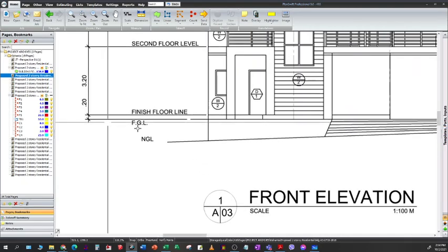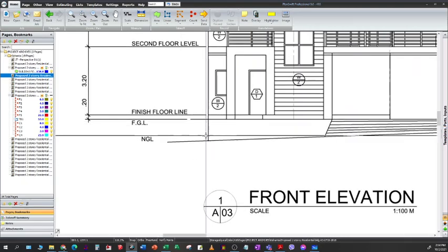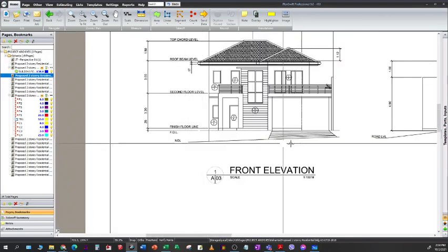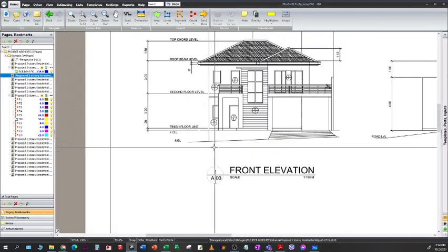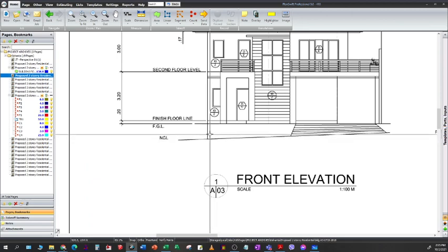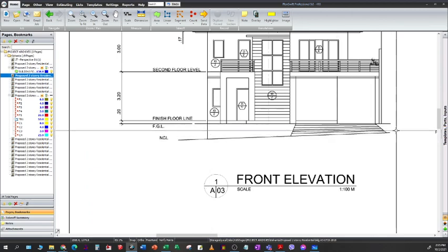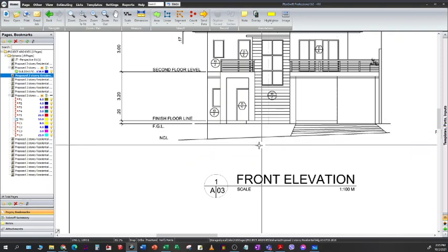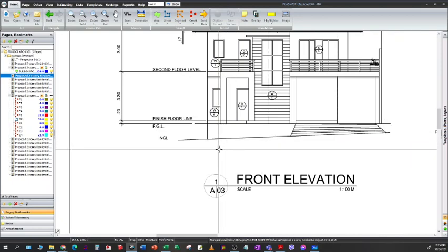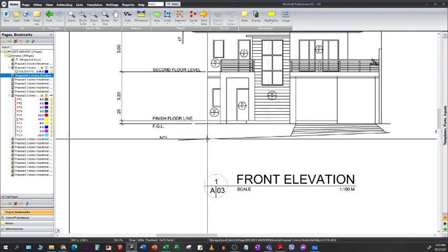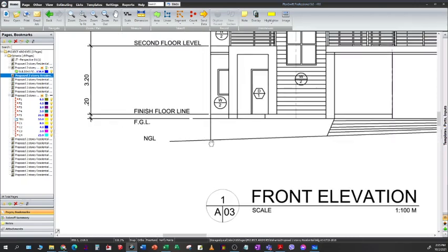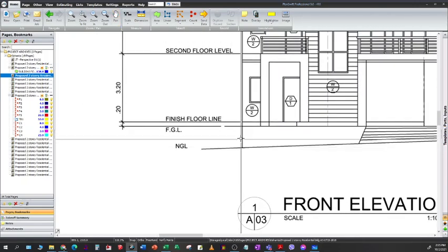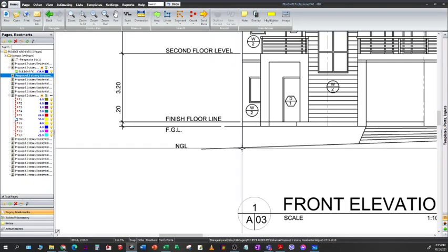And then we still have a sort of slope here in the natural grade line. So by just looking at it, we can see that there is a big difference between both sides of the building. But just to be safe, let us assume the deepest part. Okay? And the deepest part, by inspection, is estimated to be around 1 meter. So we add 1 meter to the 6.4.